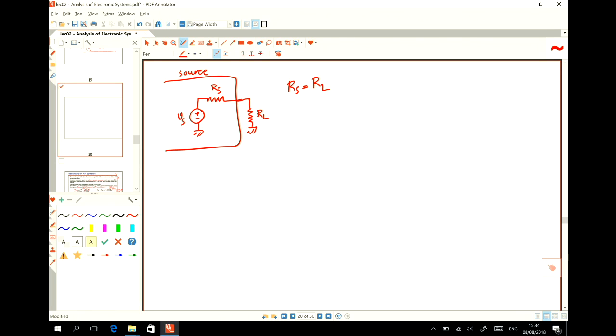Okay, what's the noise of my source? The noise of my source comes from this resistor. And then the noise that we have, I mean Vn, equals the square root of 4KTB. And assume that B equals 1 hertz. So I can model this resistor with a noiseless resistor in series with a source of Vn. I mean, I can write this down like this. We have a Vn. So here is R, here is R, and Rs equals RL equals R.